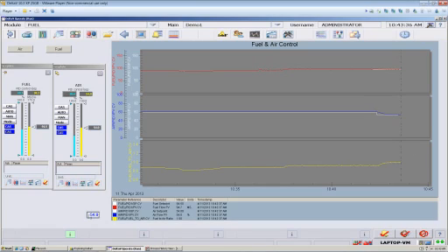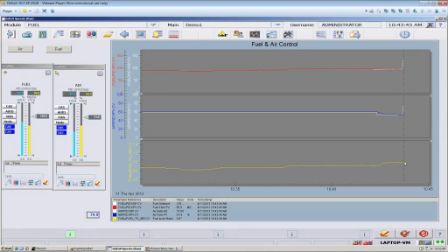Now we'll make our set point change. Let's make that big 20% change that rocked the boat so bad with the old tuning. What I expect is this: in spite of the imperfections here, the slight hysteresis on the valve, the slight noisiness of the measurement, even with those imperfections, our fuel-to-air ratio remained pretty darn good throughout, and 48 seconds later, as predicted, we came to set point.